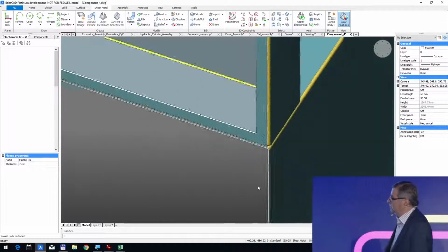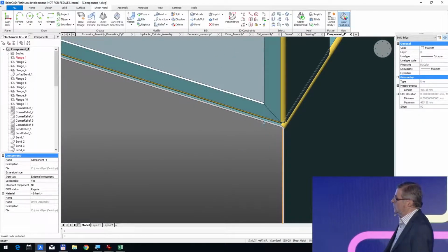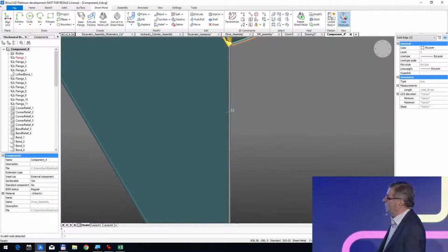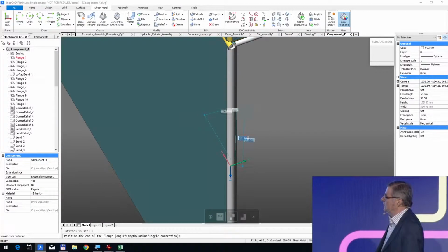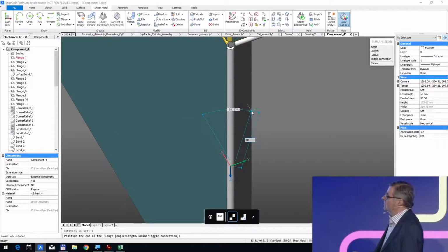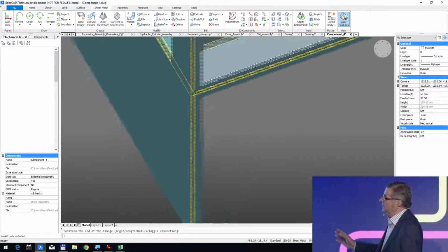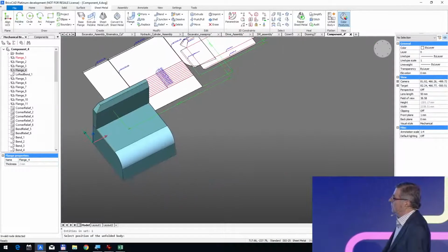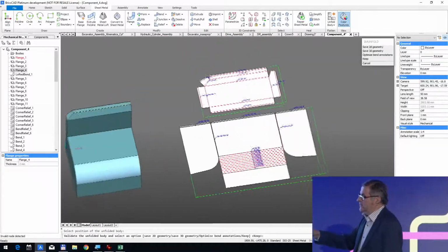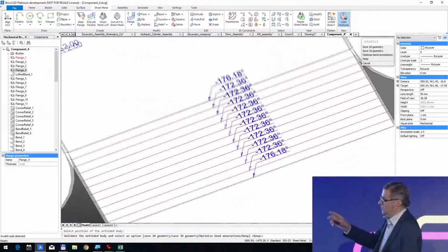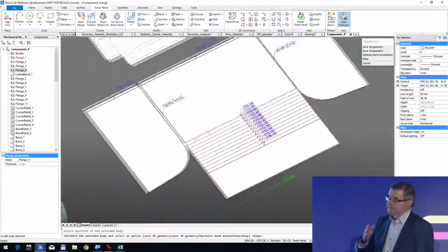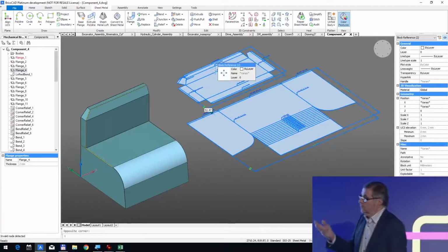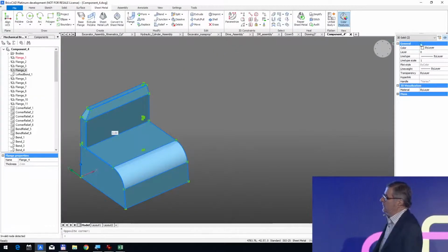And then we will create also those 3 bands, 3 parts, 3 flanges. Okay, and it's finished. And this can be unfolded. Of course, the big band is recognized automatically as a lofted band, so made by step-by-step bending. Of course, you can change it if you want, but by default, it's like that.